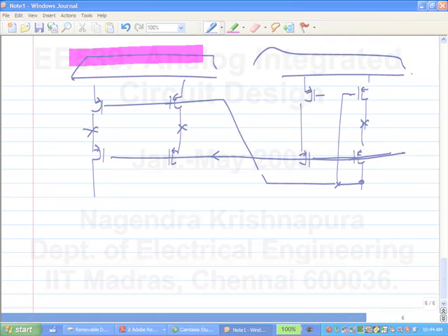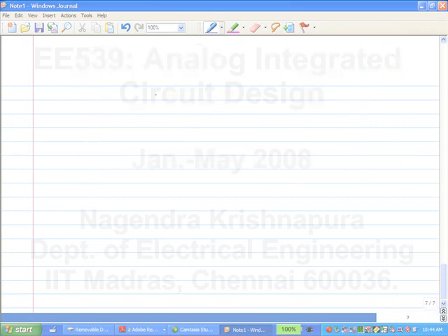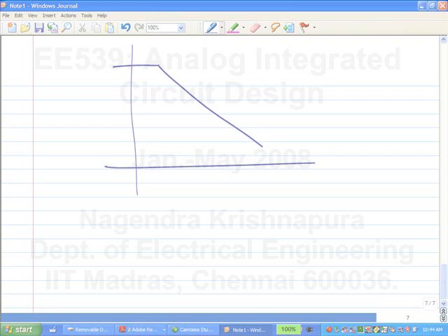Sir, when we use the CCM, it is in parallel with that RCM. The value of the CCM should be such that the zero it introduces should cancel, or be close to cancelling, the pole due to RCM. Yeah, that's correct. So perhaps the response of the common mode feedback circuit is like this without CCM.